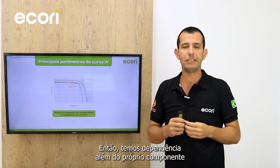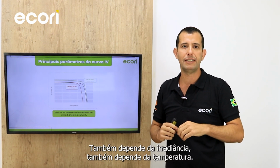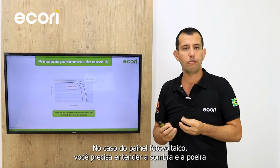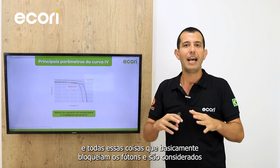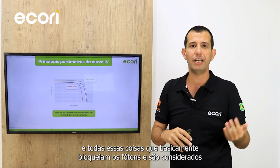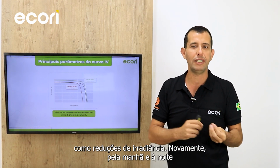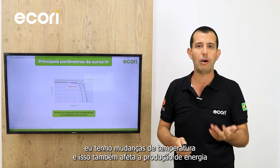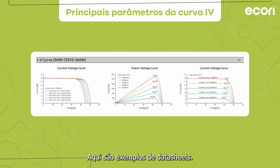So we have dependency beside the component itself. It is also dependent on the irradiance and also dependent on the temperature. In the case of a PV panel, you need to understand that shade and dust and all these things are pretty much blocking the photons and are considered as reductions of irradiance. Again, in the morning and in the evening I have changes in temperature, and this also affects the power production of my PV panel. Here are examples from a data sheet.